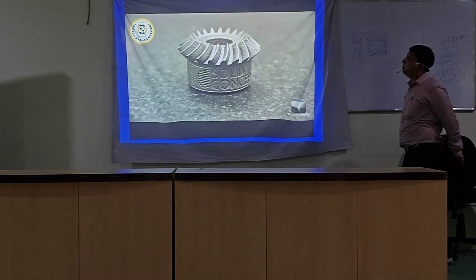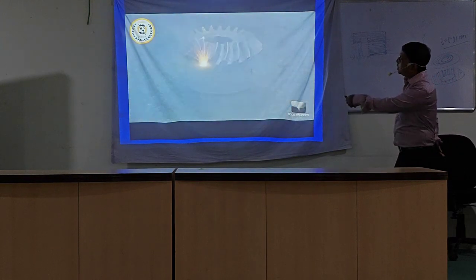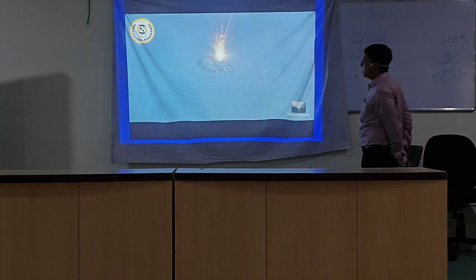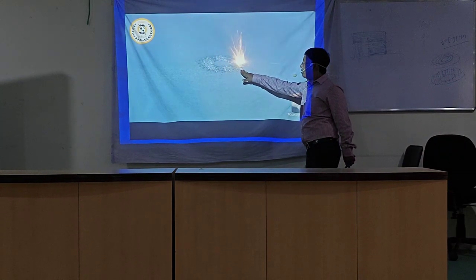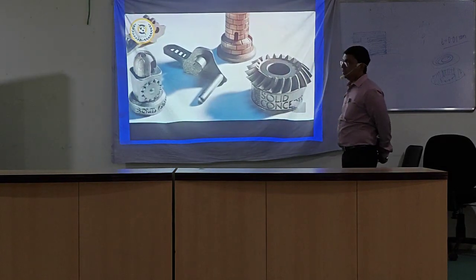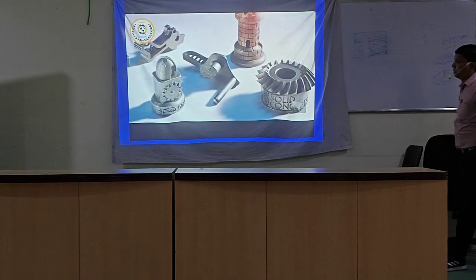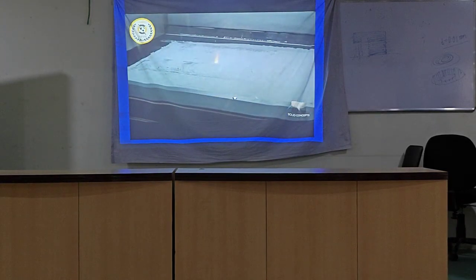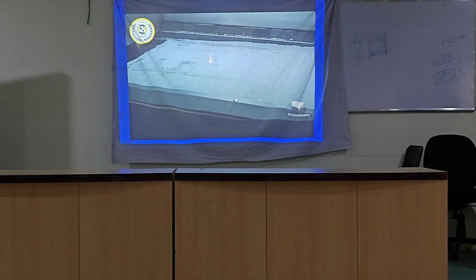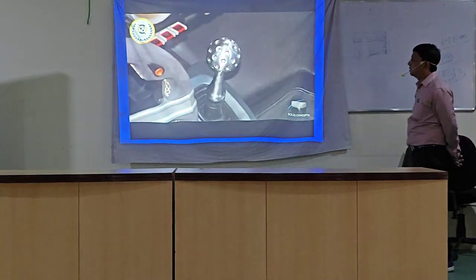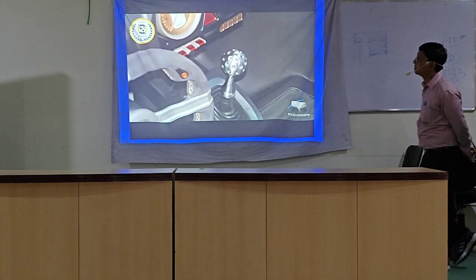This is the metal additive manufacturing, and here the powder is metal powder. So this is the interaction of the laser and the powder. Sintering process is over, one layer is over, then the powder will spread. A variety of metal and alloy materials, such as stainless steel, cobalt, chrome, and nickel, to create strong, durable parts and prototypes. DMLS is an excellent choice for functional metal prototypes, high temperature applications, and end-use parts.